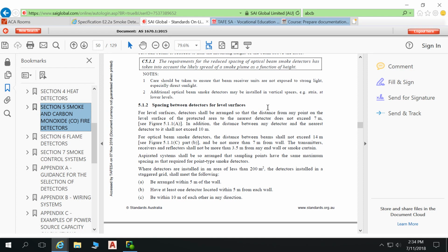And the size, and you both saw the size of those hose reels, the one from Apex Fire. So there are specifications about the sizes of hose reels. There's an Australian standard for it, but you can also just research fire hose reels proprietary systems online, and they say our fire hose reels are designed as per AS, etc., and they will reach 36 metres for a 19mm hose. So they're the important design elements in regards to that we covered on Monday.